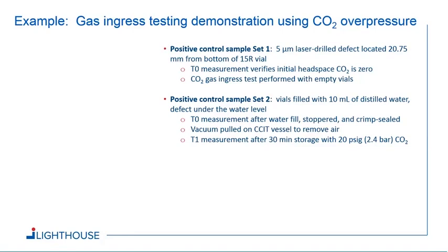A measurement of the headspace CO2 was made to verify that there's basically 0 levels of CO2 initially in the vial. And then these vials were placed into a CCIT vessel and overpressured with carbon dioxide. After this overpressure, we took the samples out and measured the headspace CO2 levels with a headspace gas analyzer.